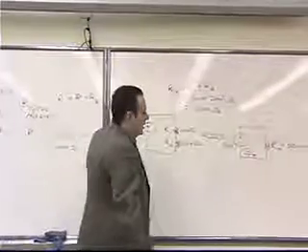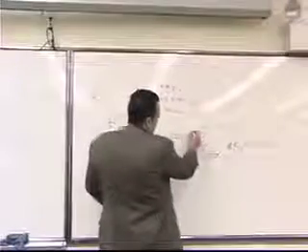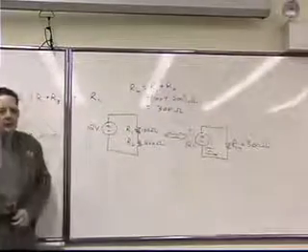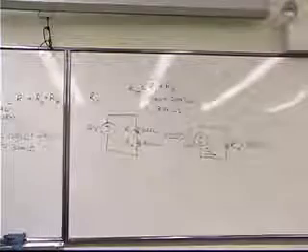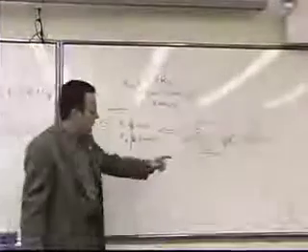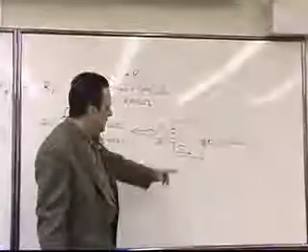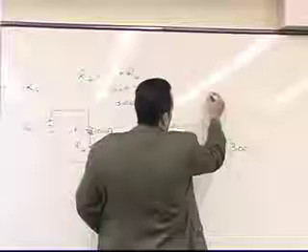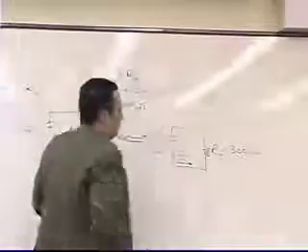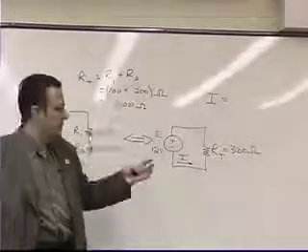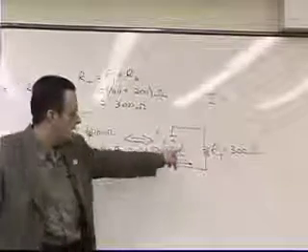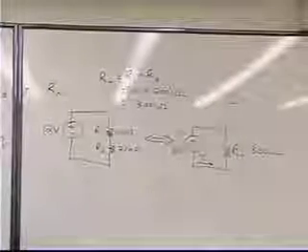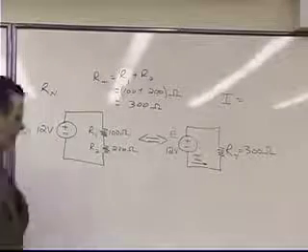And if we know what the voltage is, in other words, we know what E is, and sometimes that's called V in some books. In our book, it's called E. And we know what the total resistance is, but we're looking to find the current, then we want to look at our Ohm's law formula wheel for a formula that says current is equal to something in terms of E and R. So what would that formula be if you look in your book? E over R. E over R.